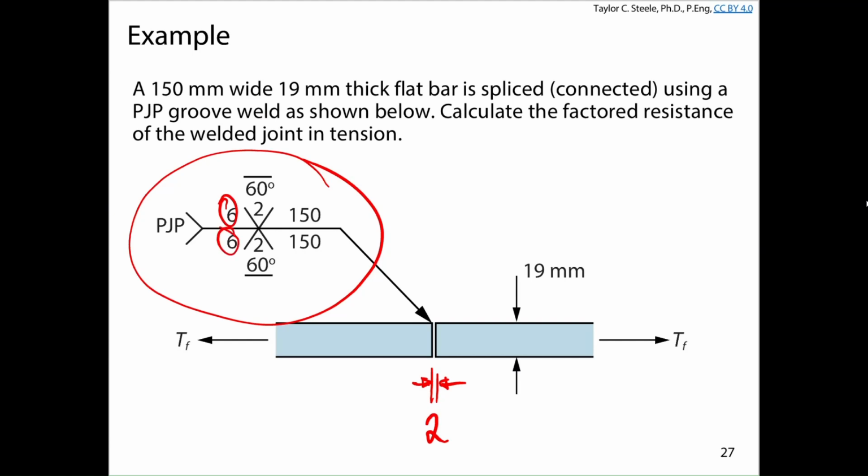That's the effective depth or height of the weld. So we're basically coming in here and we're going to bevel out a little bit at 60 degrees with weld material. Right, and that's this one. The stuff on the bottom of the line means this side of the arrow. And then we have this.